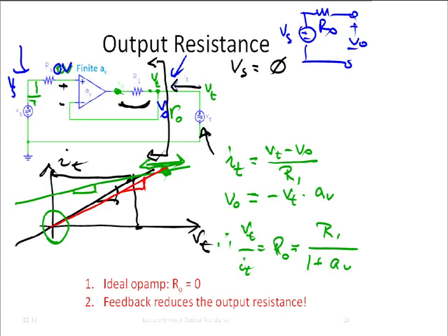But there are, of course, cases where a few millivolts is the whole error. If I build a thermometer and the output of my transducer is only 1 millivolt per degree, and I have 2 millivolts of offset, right from there I have a 2-degree error. So there is more.